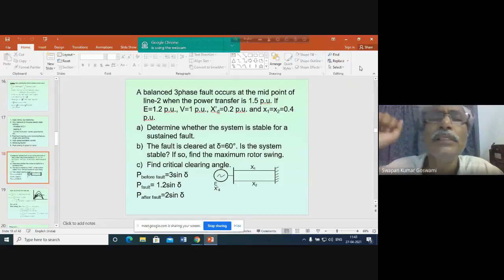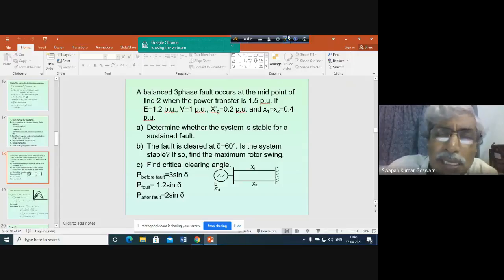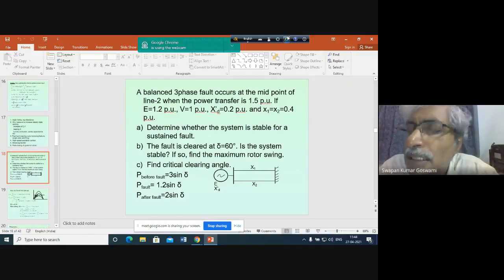During a transient stability study, the period that will determine whether the system will be stable or not is the period when the generator will be in transient condition. That's why during transient stability analysis, the generator has to be represented by its transient reactance.